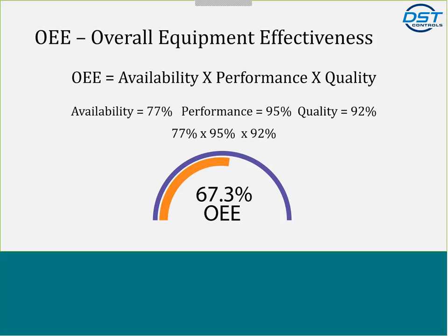Now, when I first saw OEE and these calculations, the first thing that I thought was remarkable is, man, 67.3, that's kind of low. When I look at these three numbers, we're not up in the 80, 90% range for our OEE. We're actually at 67.3. So the first thing to realize is this isn't an average of the three. This is actually a multiplication. So if your availability drops to 50%, you're never going to have an OEE that's above 50%. That's just something to keep in mind when you're looking at what an OEE number actually is and what you're trying to achieve.